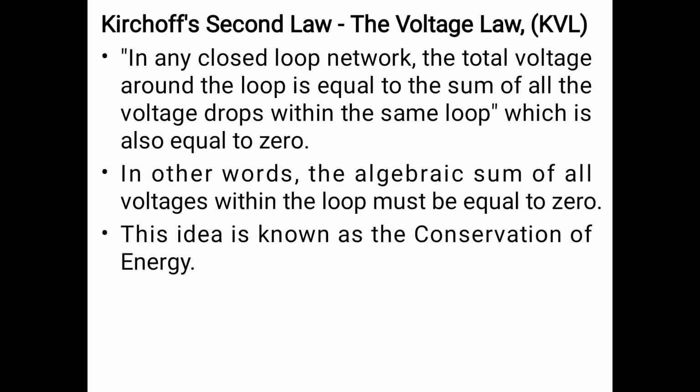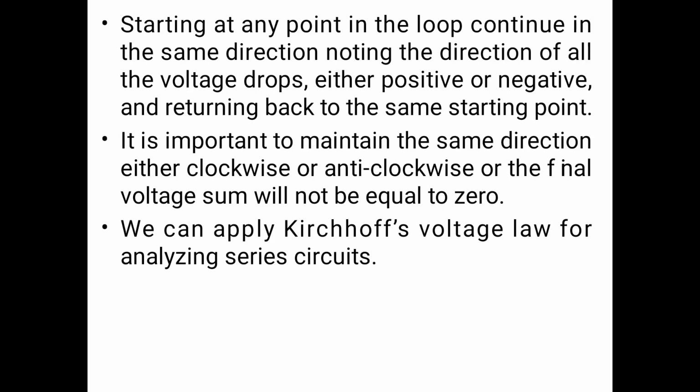Kirchoff's second law, the voltage law. In any closed loop network, the total voltage around the loop is equal to the sum of all the voltage drops within the same loop, which is also equal to 0. In other words, the algebraic sum of all voltages within the loop must be equal to 0. This idea is known as the conservation of energy.